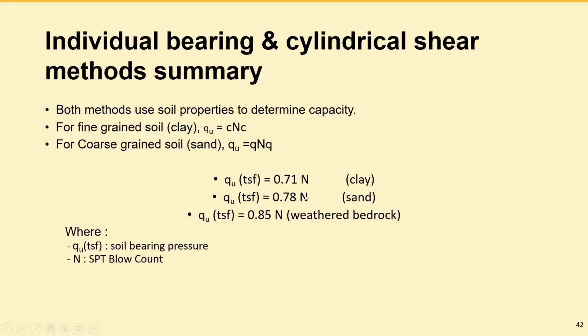So I would like you to take these numbers over here. These are empirical relationships that we came up with when we did all these tests in Colorado. Clay and sand are different from other states, but we did this in Colorado, we did hundreds of them. What we did was install these piles. We have the boring logs, we have the blow counts, we know exactly how much the blow count is at the level of the helix, and we know the torque. We installed them and we tested them.